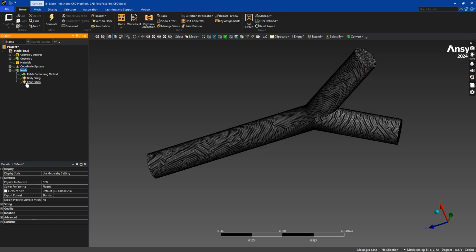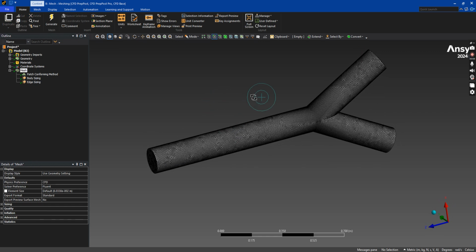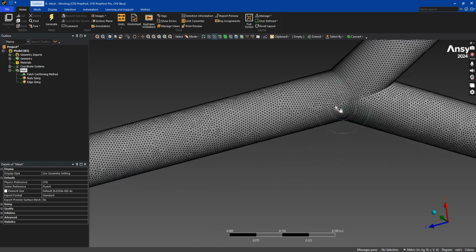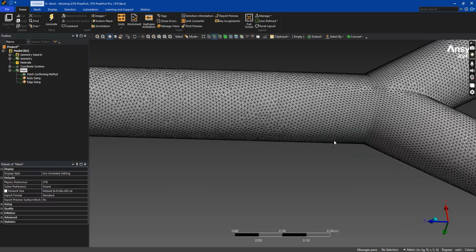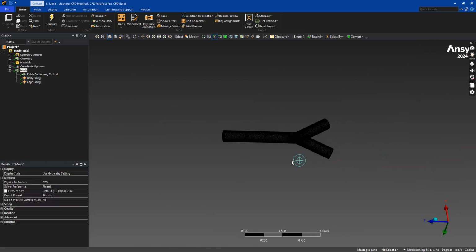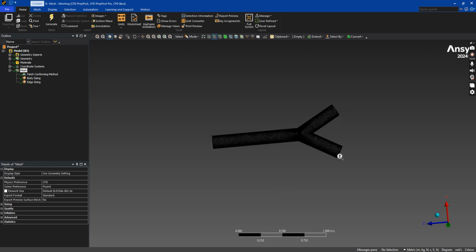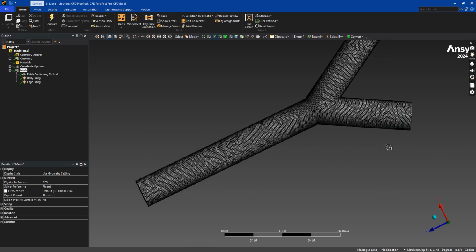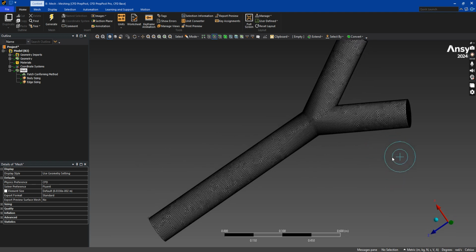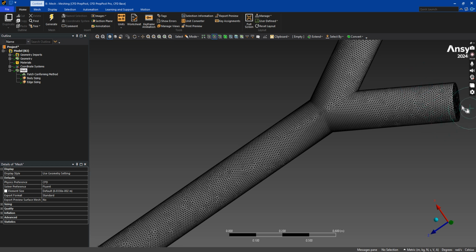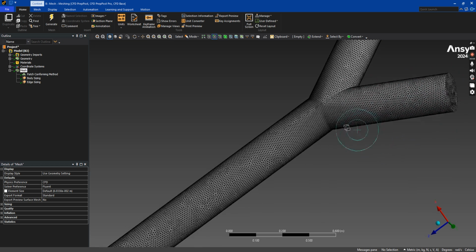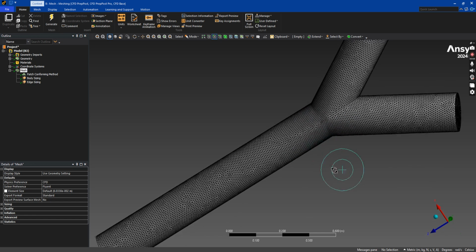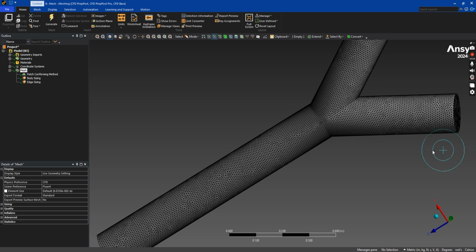Now let's look at our meshing, and you can see a much finer meshing in here. Alright. Well, I don't see a basic difference in the meshing here. It's the same mesh as here, but at these edges the meshes are perfect, but not at these edges. So let's give a separate edge size at this inlet and outlets.